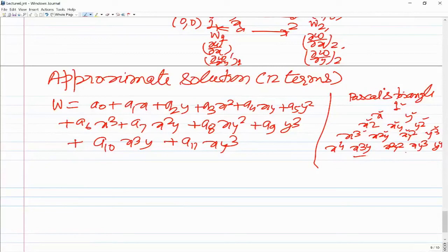So we are giving preference to those variations rather than x power 4 and y power 4, so that when the element is smaller and smaller, it gives the exact solution. If you have x power 4, y power 4, and the variation of w is proportional to x cube and in the y direction y, that would be missed out. So we give preference to the lower terms compared to the higher power term.